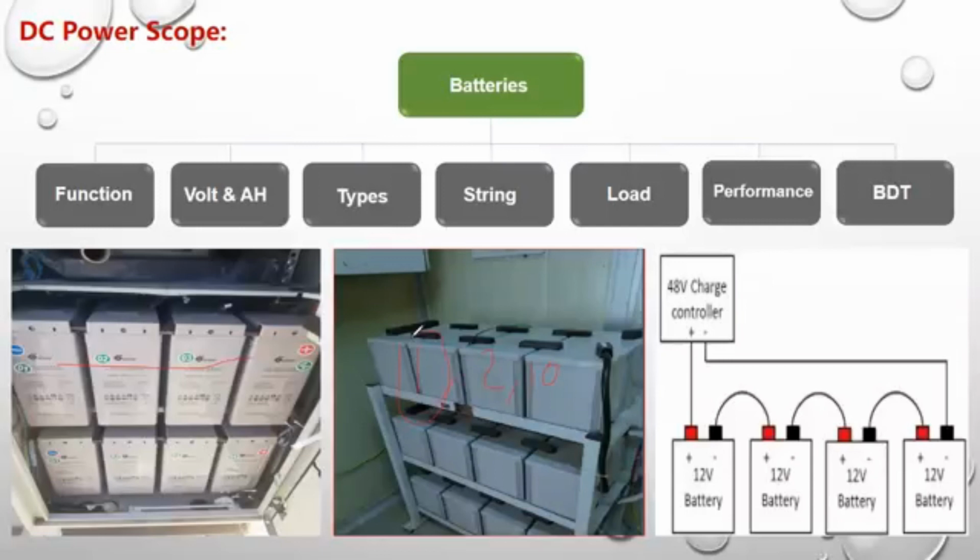The second thing is dust. The batteries have pores for ventilation in a way. The dust enters these pores and destroys the ventilation process of the batteries. So that's why regular maintenance is done to clean the dust. And it's better to dry dust first with a blower or a dry piece of cloth. If you, for example, used water first, this dust will turn into mud.